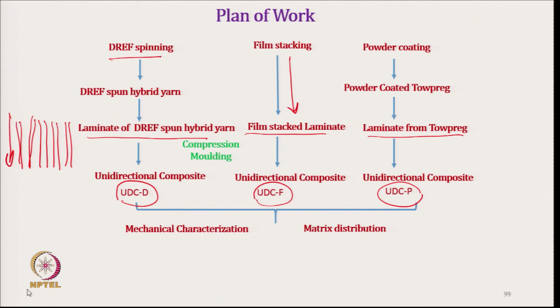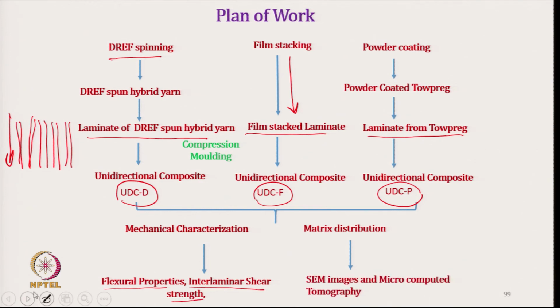And then we will study their mechanical characteristics and matrix distribution. Mechanical characteristics will be studied using flexural property and interlaminar shear strength, and matrix distribution will be studied using scanning electron microscope and microcomputed tomography. This is the total experimental plan.